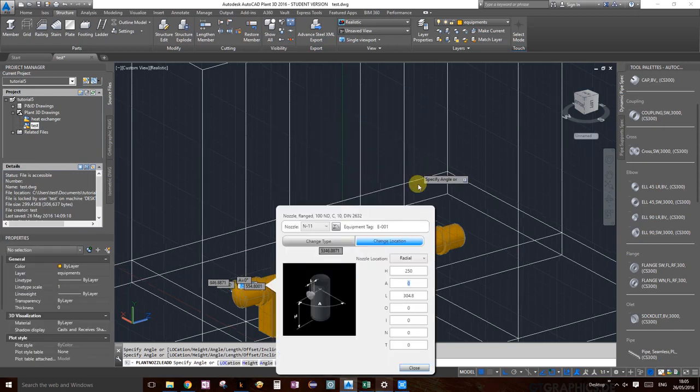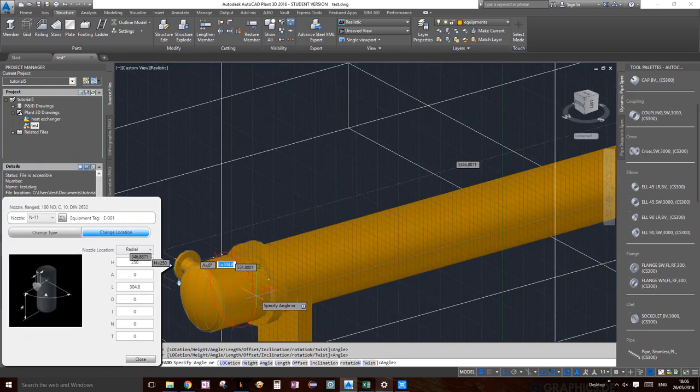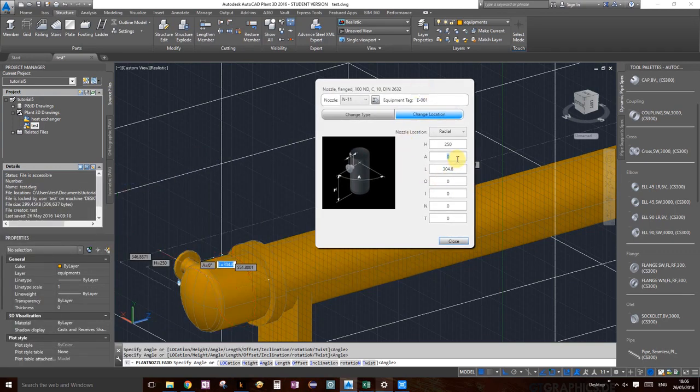An angle, we want it at 0 angle for sure. Actually, no, we don't want that, we want it at 90 degrees. All it's going to do is, right where it is right now, you can kind of see it, see, it's here. We want it facing upward toward the ceiling. So let's put that to 90 degrees, and the length is how much it's going to stick out.